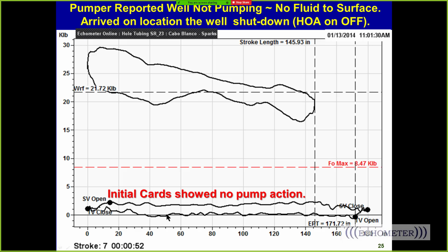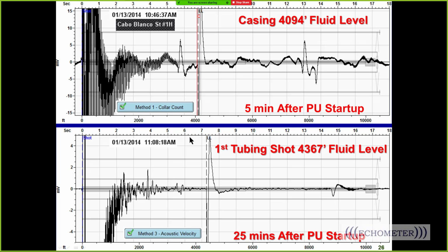If it had been a horseshoe load cell, it would have been shifted a little bit above the zero load line, because the tubing is partially filled with gas and partly full of liquid. And it's got overtravel, probably fiberglass rods, pumping fairly fast. But there's no rod stretch because there's no fluid load. So that's another reason why there's a much longer pump stroke than surface stroke.